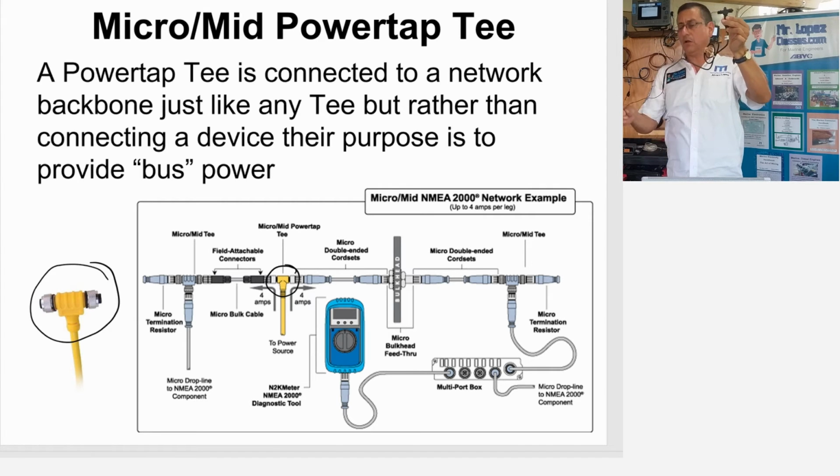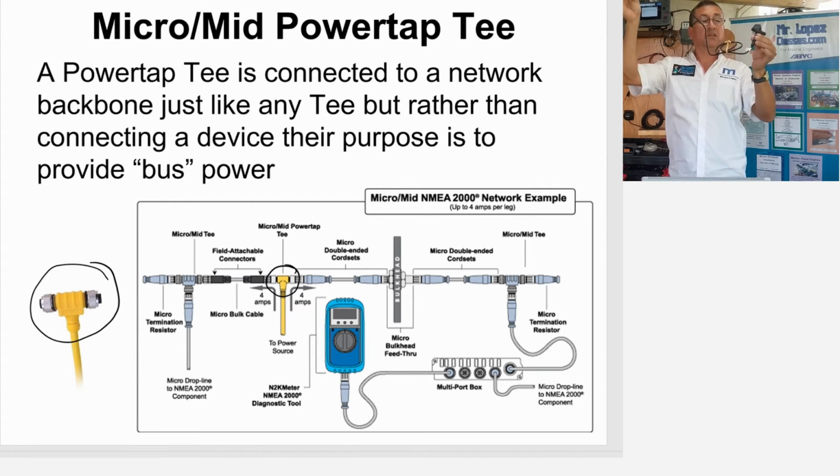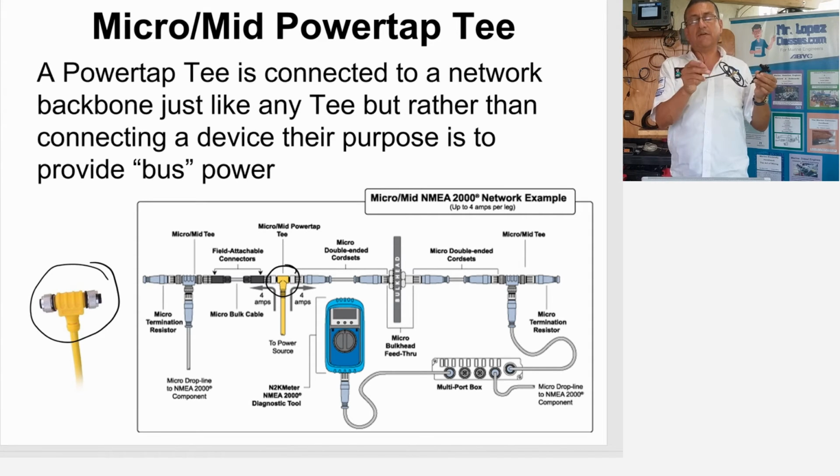and I introduce the T in the backbone, and right now my power enters in this cable, and the color is black, but I have two cables, one positive and one negative, the negative to the negative bus bar, and the positive with a fuse into the DC panel. That's for power.